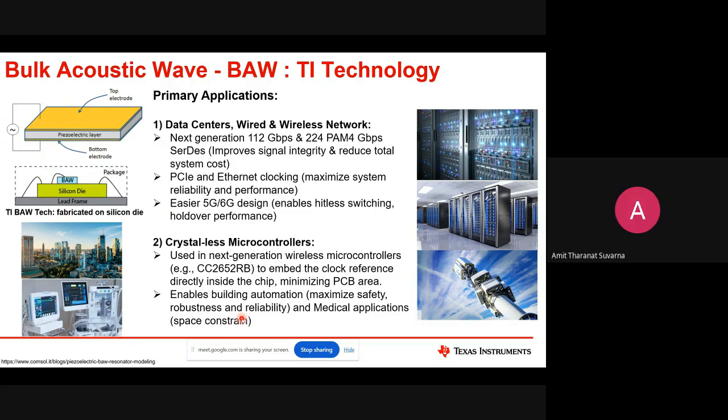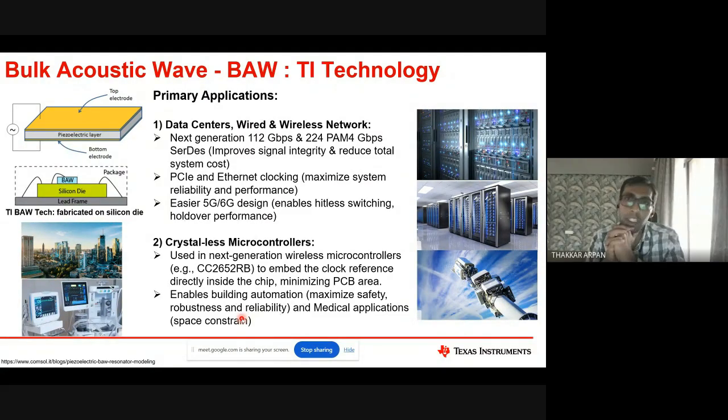So how can I reject that? What is the concept for that? Okay, so what they do is they use different supply domains. So it remains a challenge. You are correct. Sometimes a lot of our chips are based on this BAW, right? They support, like, 12 channels. So one BAW can generate 12 different frequencies, let's say, right? Now those frequencies are different values, so they can interfere and cause spurs in each channel, right? So that always remains a challenge.